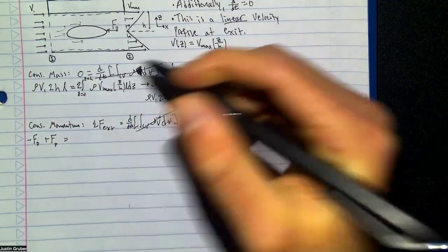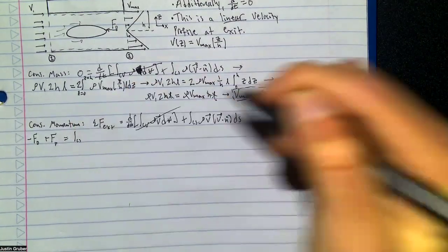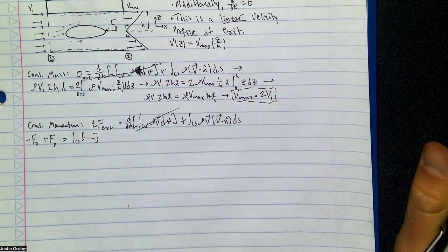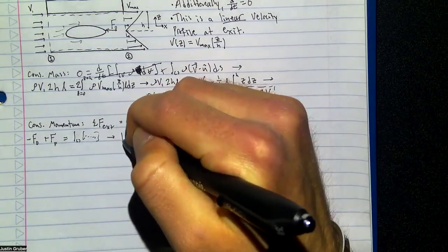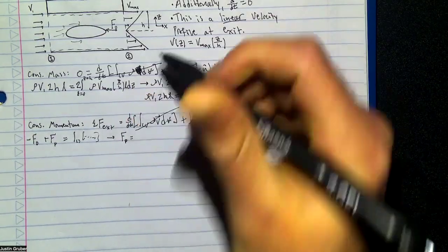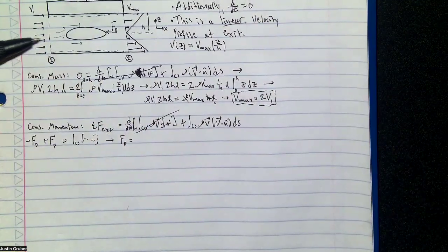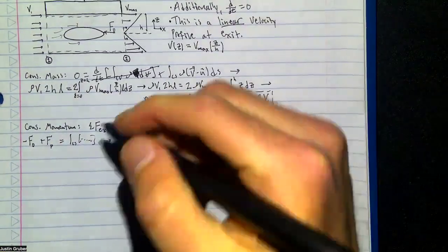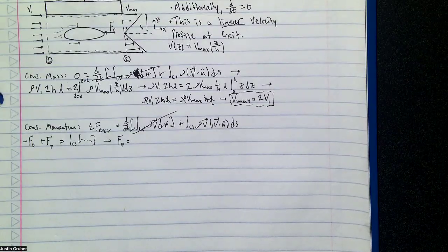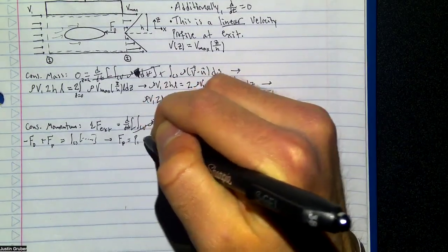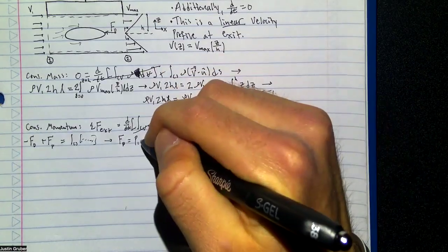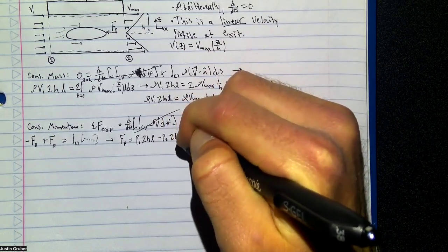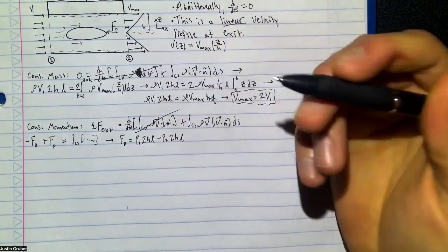Equals, again, that goes away. And so now we just have this CS term. What I want to do is find these pressure forces first. FP equals some pressure pushing up on this side, and then some more pressure pushing over on this side. Thinking about what direction they're pointing, you have a positive P1 times the area, which is 2H times L, and then minus P2 times 2HL, because that's pointing in the negative x direction. Pretty easy.